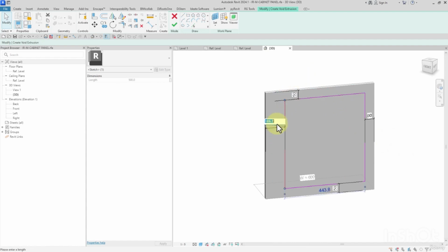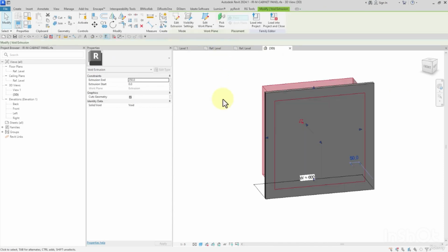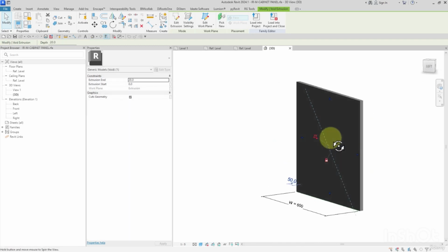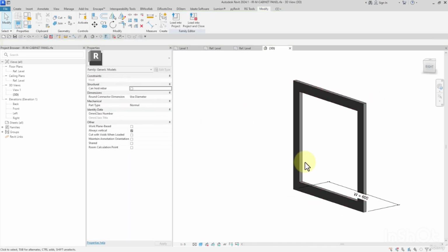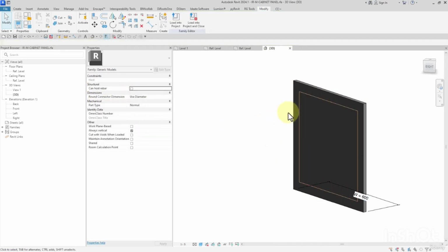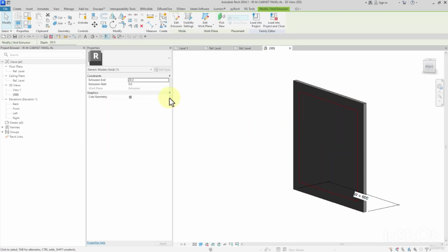By default, fixed. Very well, and then I lock them since they are going to be fixed. Finish. Then for the depth, we adjust it based on the panel. Then we select the void. Here I uncheck cut with geometry, but if I select it, it will be cut.